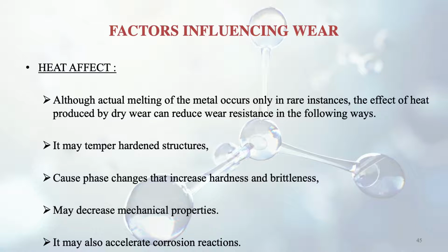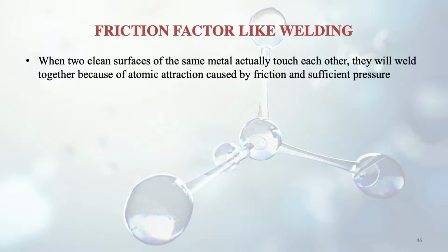Then the friction factor, like in the case of welding. When two clean surfaces of the same metal actually touch each other, they get welded together. Why? Because of the atomic attraction, which is caused by friction and sufficient pressure. So this is called the atomic type of welding. There is no electrical heating or gas heating.